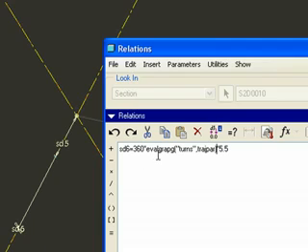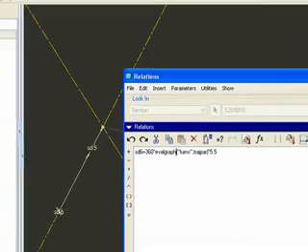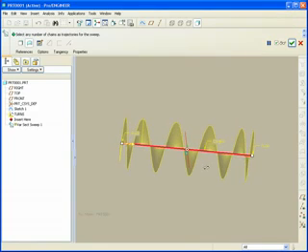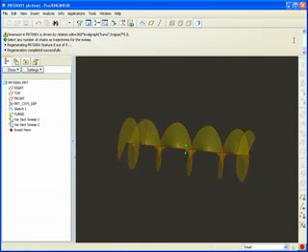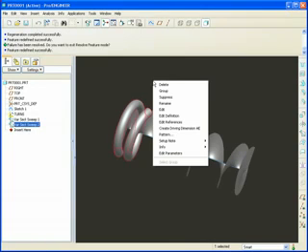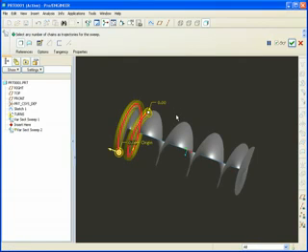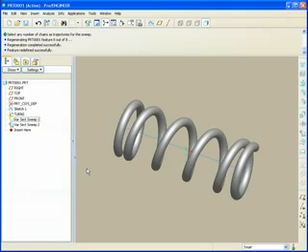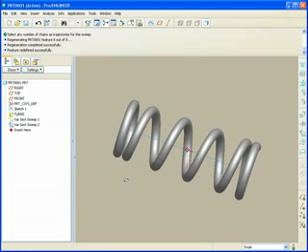So that means evaluate the graph, PH, evaluate the graph called turns along its x length, returning the y value for every x. When I call this sketch done now, you see that same corkscrew has now got compressed ends. And if I want my protrusion now to reflect that same change, edit the definition, holding the shift key down, right click until I get my tangent end. I'll go back now and hide the corkscrew, and you can see now I've got some very nice compressed ends.